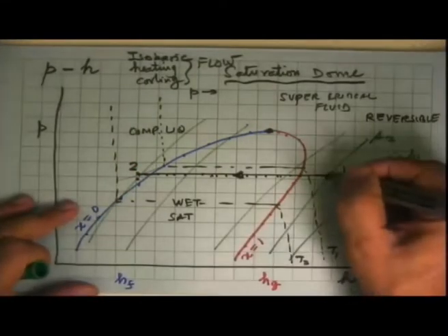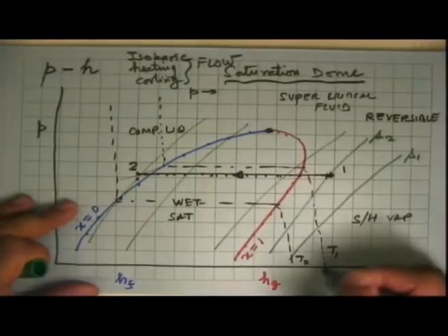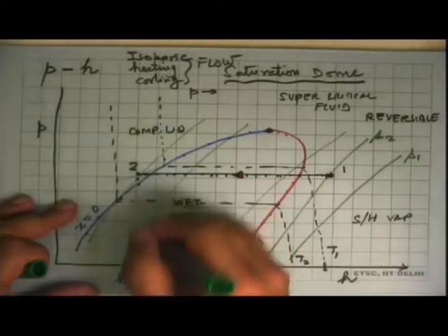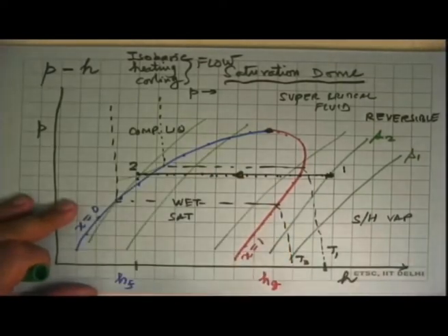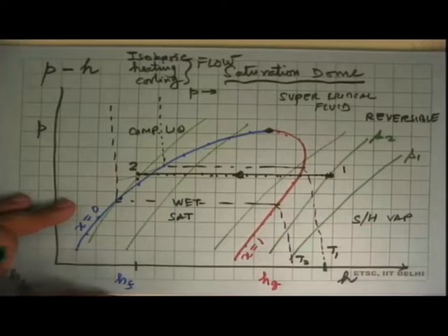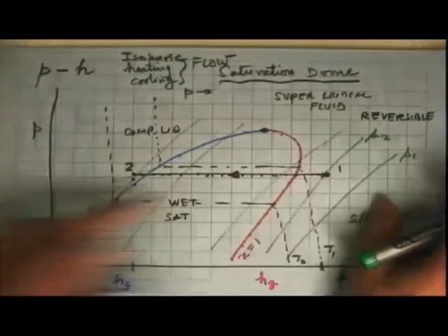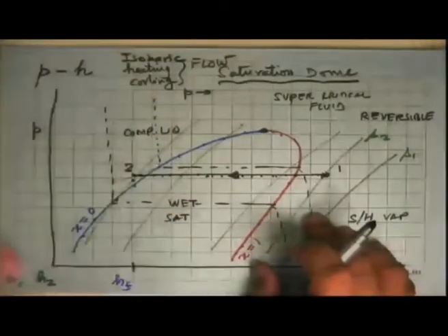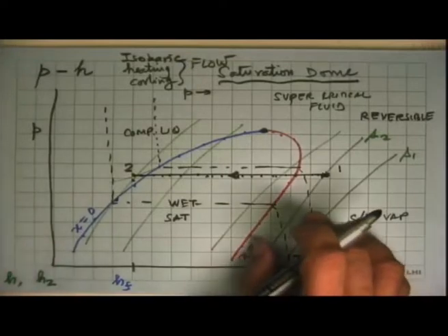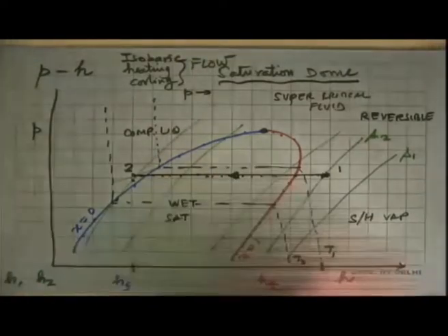That is quite nice because you can just go down this chart, look up this value of the specific enthalpy, go down this point, look up this value of the specific enthalpy. We can get H1, we can get H2, and the difference of this is the enthalpy drop during the process. That multiplied by the mass flow rate is the heat transfer in this process in steady state, no change in kinetic and potential assumptions. That's a nice thing to know.